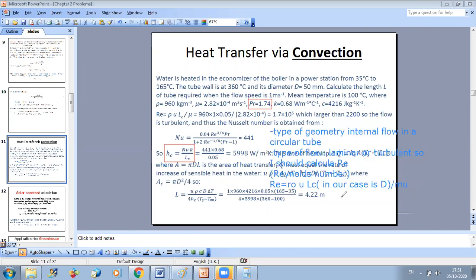If you encounter it in a certain problem, the difference is just that the dynamic viscosity mu is equal to the kinematic viscosity times rho. So if in a problem they give you the kinematic viscosity, all you have to do is multiply it by rho, and you get mu. Here they directly give us mu. This is the symbol of the dynamic viscosity, and this is the symbol of the kinematic viscosity.